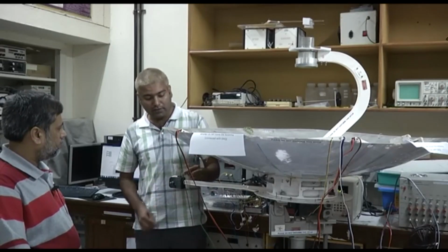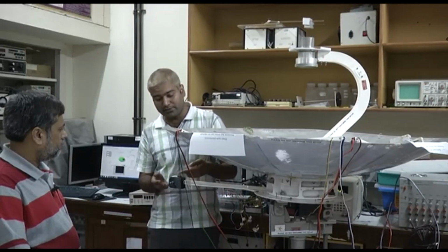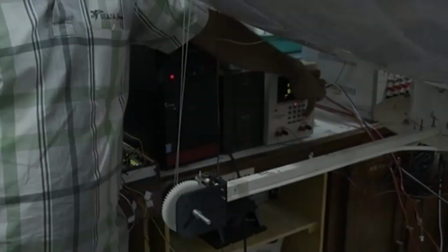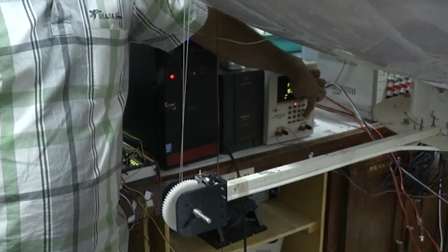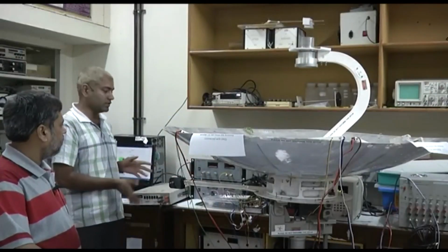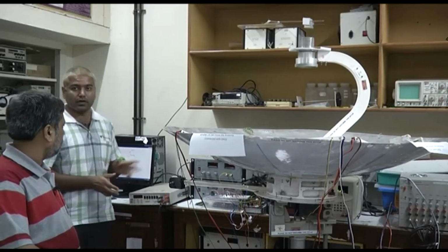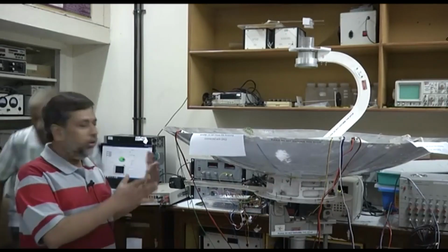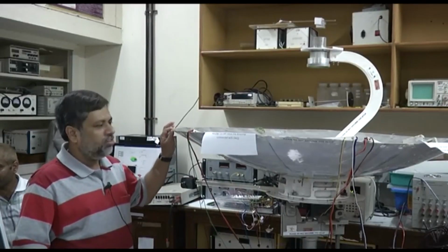And for unlocking, we are using SMA springs, and this ratchet will be unmeshed from the pulley, and my antenna will get back to its original shape as it was before. So now we are developing the control system to control it directly using our controller, that is PC or NI DAQ card. Okay, so thank you, Shahil. So we have just shown you how a shape memory alloy wire based system can work and how you can control the shape of it.